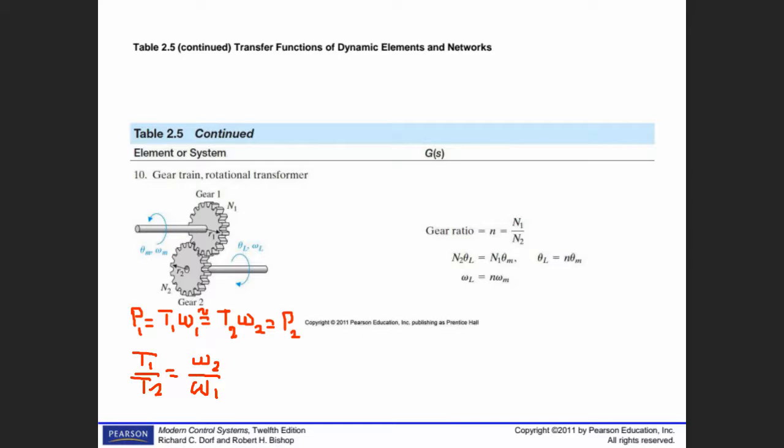Since power is the same, if you rotate it fast, that means speed is high, for example, for an electric motor. Speed of the electric motor is high. That means torque is low. If you increase the speed, follow me, then the torque goes down for the same power. Less torque means less current. Less current means less conductor, so it makes the electric machine smaller. That's why electric machines for electric vehicles run over 10,000 RPM.